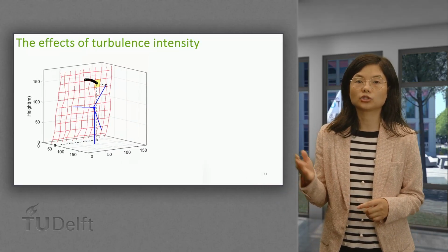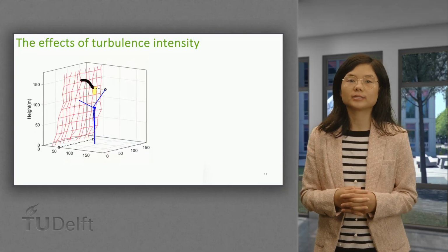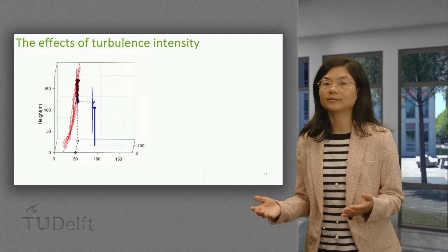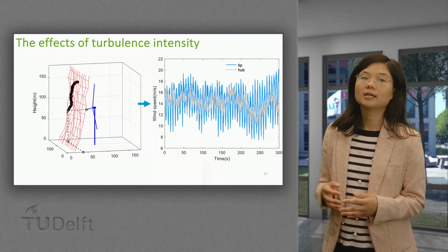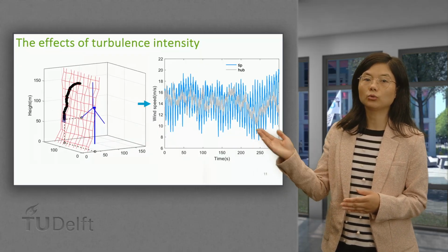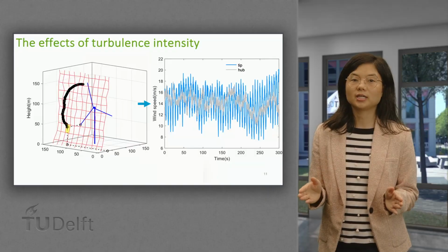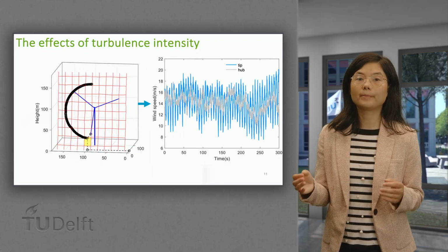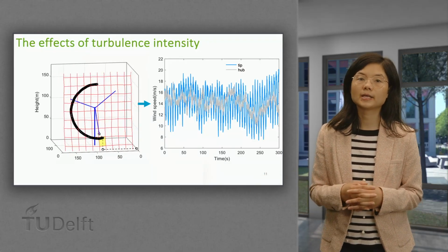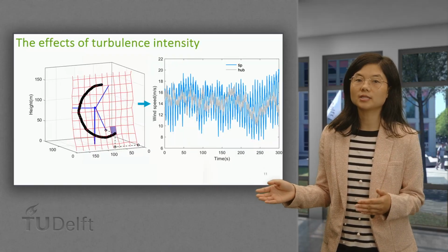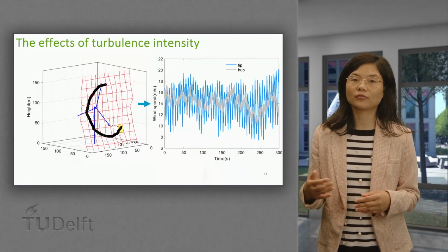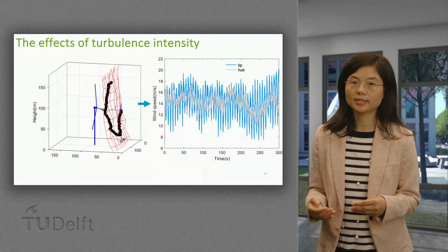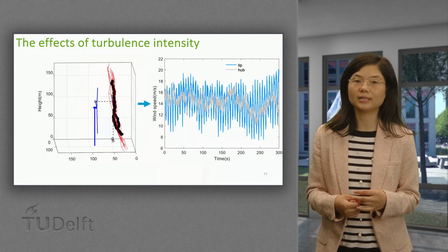The animation on the left shows how one blade tip experiences fluctuating wind speed due to random turbulence and vertical wind shear. The right figure presents a time series of wind speed measured at 2 points: the hub height and the blade tip. Fluctuations at hub height are caused solely by turbulence. Blade tip fluctuations resulted from both turbulence and wind shear. These random wind speed fluctuations due to turbulence can increase fatigue loading on wind turbine components, reduce rotor efficiency, and affect power output and control stability.